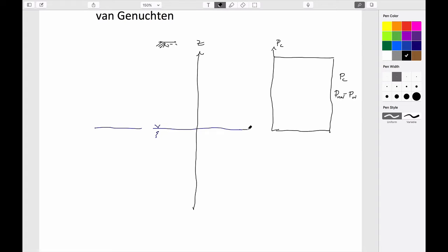And this is pressure, not capillary pressure, but it could be any of the different fluids that we talk about. Then we know that if we had, for instance, water, then the distribution is supposed to be blue, might not show up very blue. The distribution of pressure with depth would look like this. By definition, the water table would be at this level. And if this is 0, then are we using gauge or absolute pressures? Gauge, yeah. Excellent.